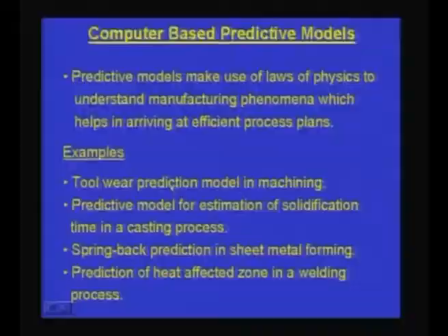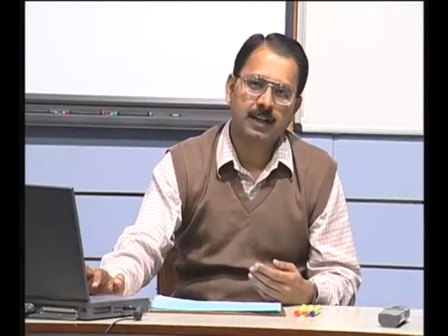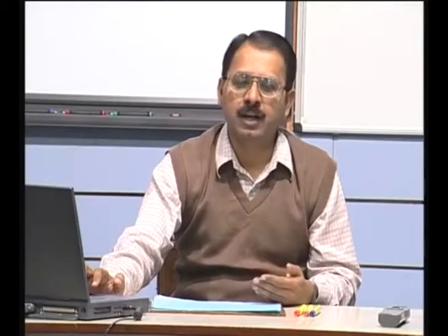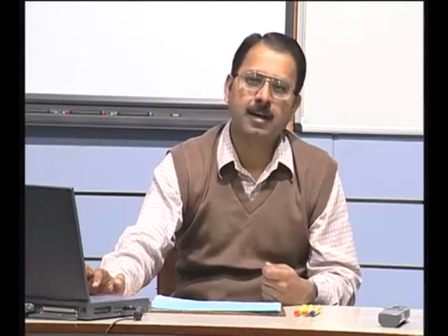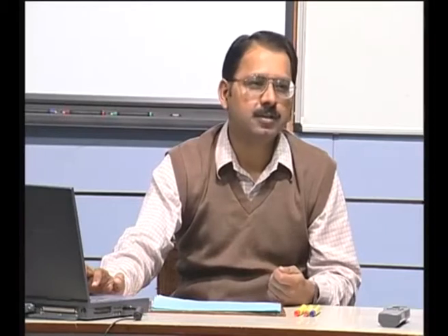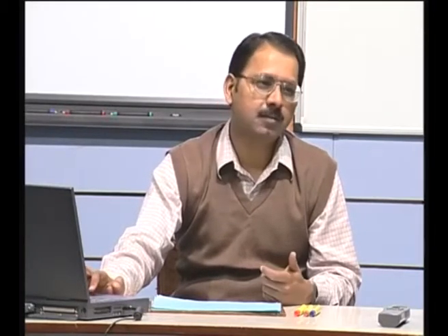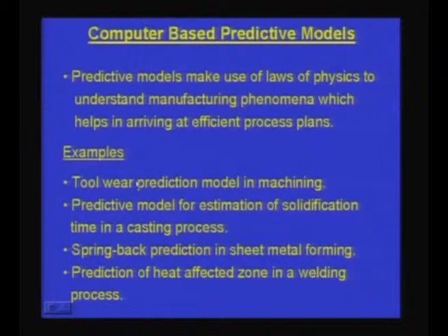If I have a mechanics based model which can tell that the life of the insert is going to be so many minutes, then that will help in terms of when the tool replacement should happen or when the insert should be replaced. So, you are using a mathematical model which may be analytical or computational or numerical to predict what would be the tool wear.